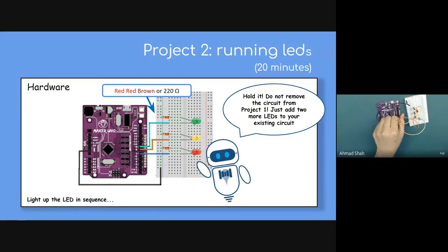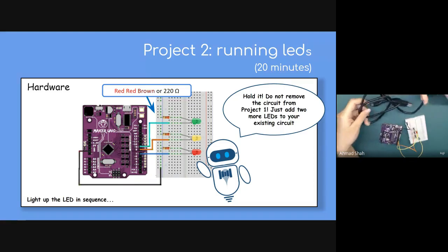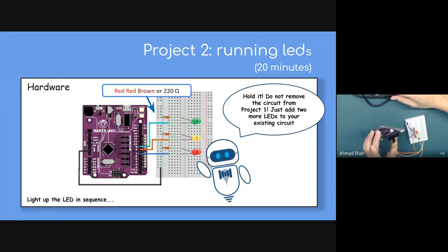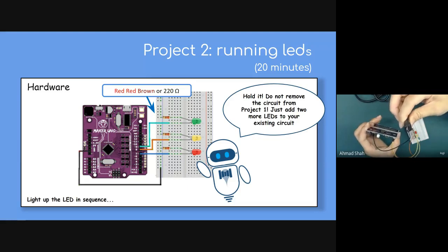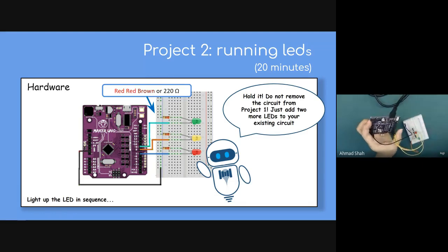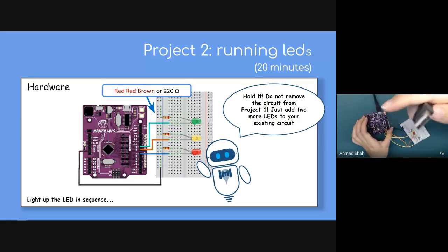Okay. So now it's time to connect the Maker Uno to your laptop. You will take your USB cable. This is a messy cable. You can see this connection, right? You just plug in this micro USB, and then this USB-A will connect to your laptop.